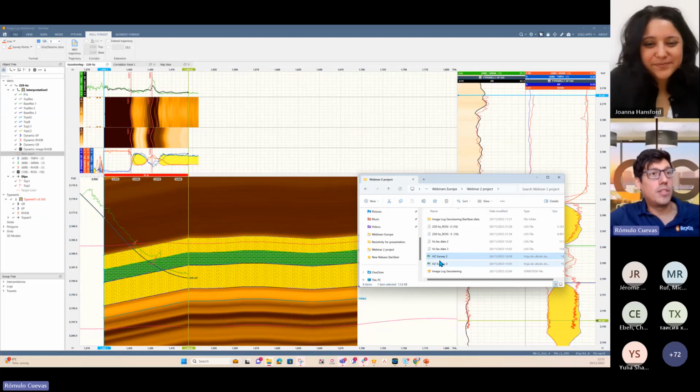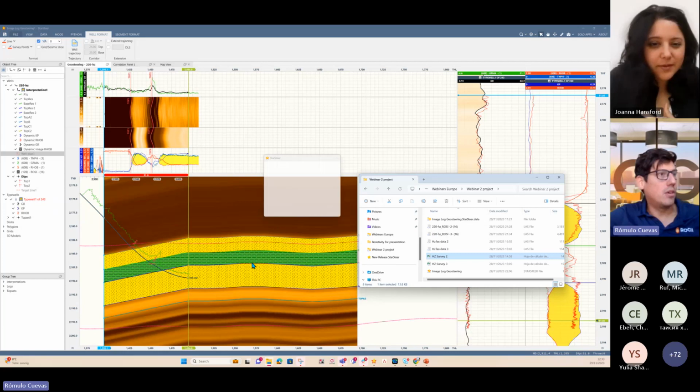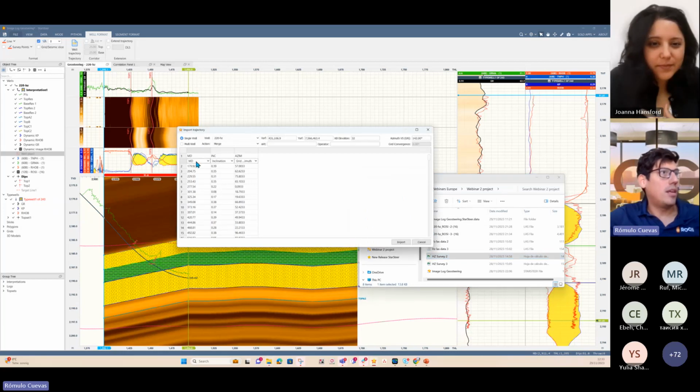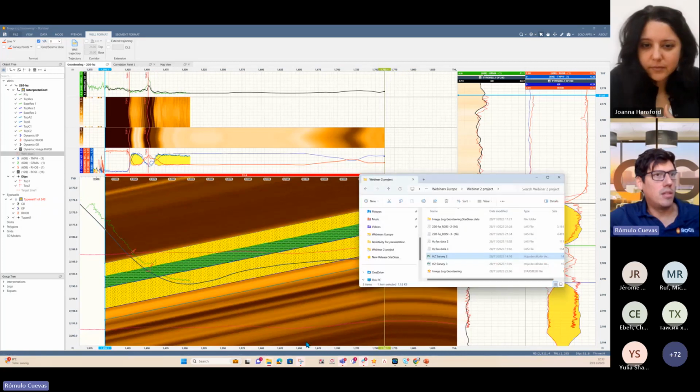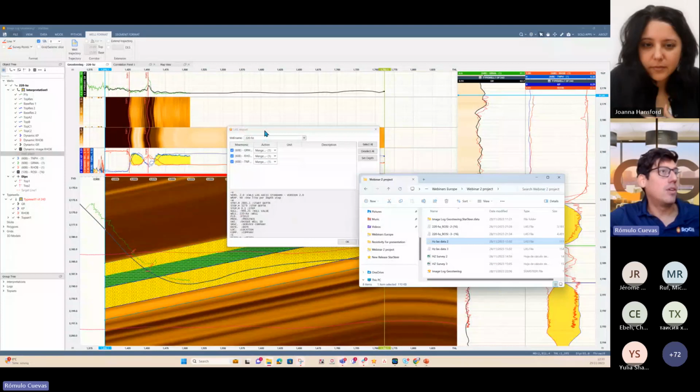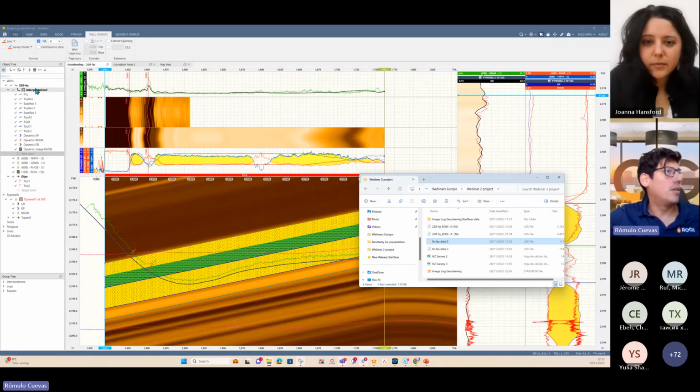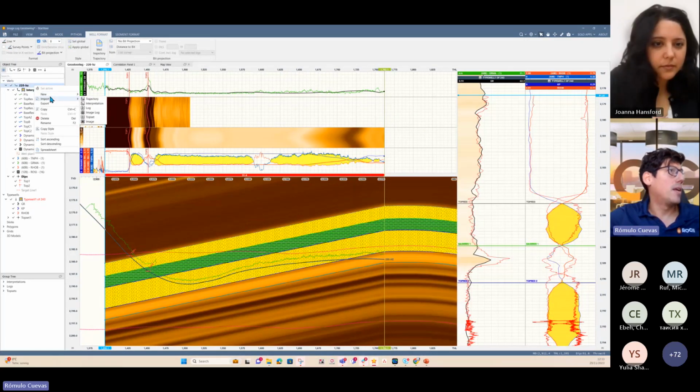So I'm going to load. In Stratigraphy, you can drag and drop data to load. So I'm going to load the second survey here. I choose MD, inclination, and azimuth there. And the action is merge. So I'm merging, and I get more trajectory. And then I will also drag and drop one more file. So I'm going to merge gammas, density, and porosity. Okay. And I will add another piece of my image log.